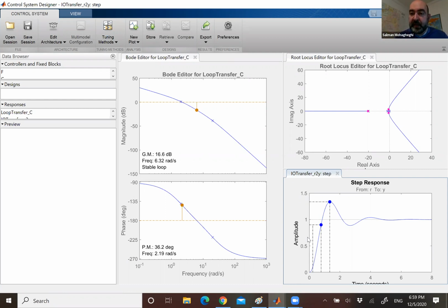When you're adding positive angle, that means you're improving your phase margin. And phase margin is directly translated into stability of your system, or the damping level of your system. So this is why, at least in explaining through the frequency domain, a PD controller can help your system with achieving more stability.